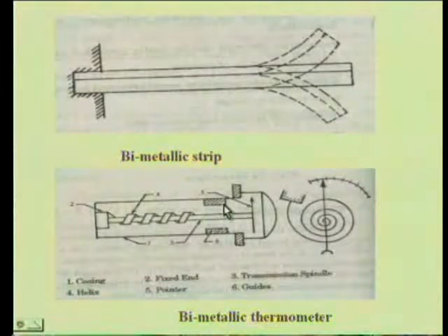Now the fixed end is connected to the hot environment, as a result of which the two metallic strips which are in helical form will expand or deform due to that hot environment. That is, heat is transferred to them, and as a result the expansion or deformation in the strips is transferred to the pointer, and the pointer moves or swivels, which will be read as a temperature.